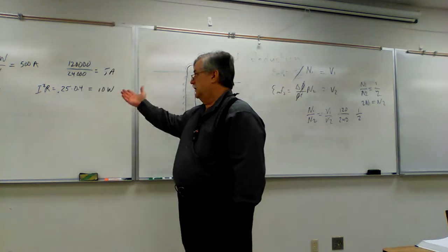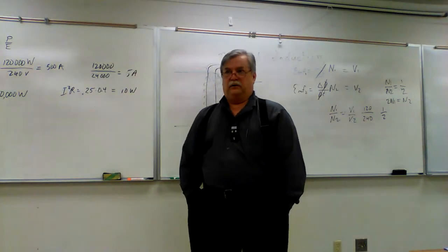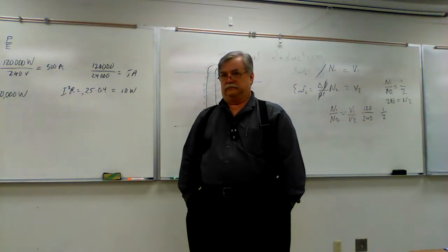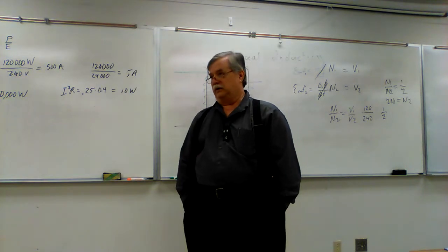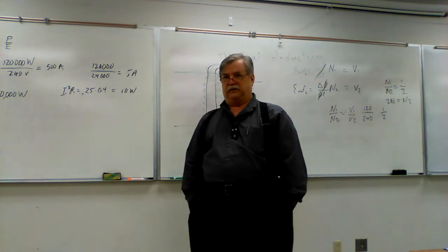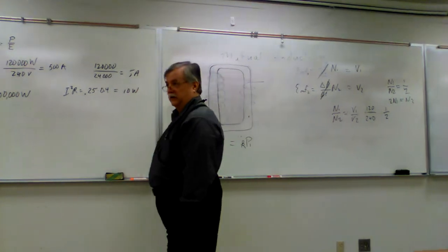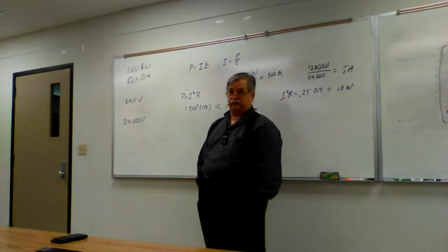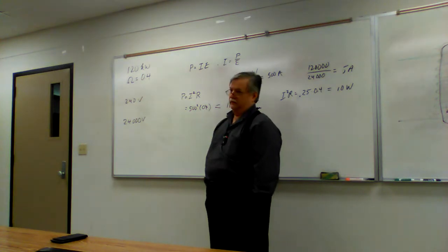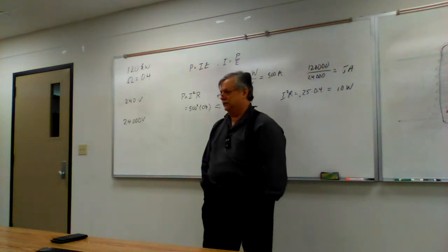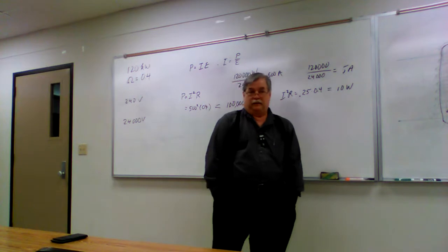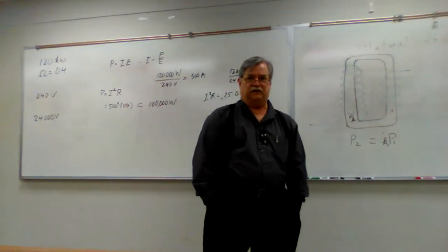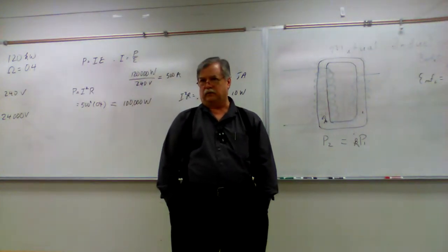And of course, you can't use a transformer with DC power. You can, but it takes a lot. You have to put in like a multi-vibrator. You basically have to take your DC current, convert it to AC, pump it through a transformer, re-rectify it. What happens if you hook up a DC current to a transformer?